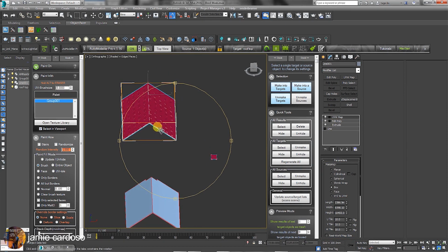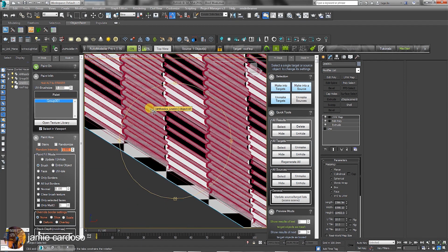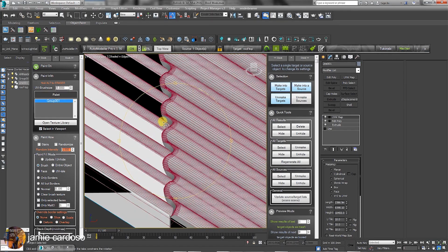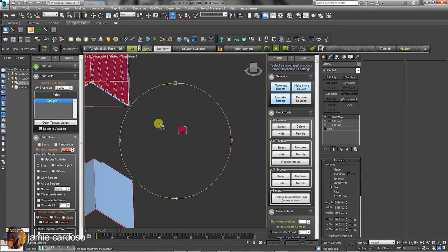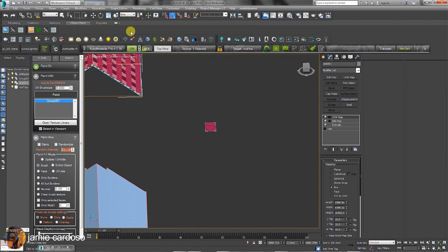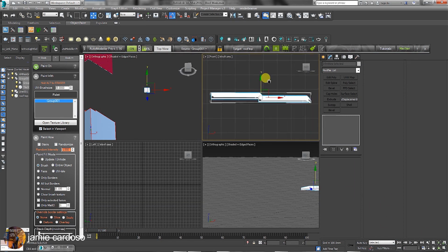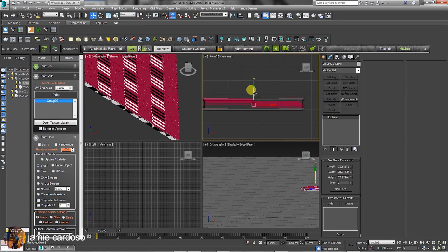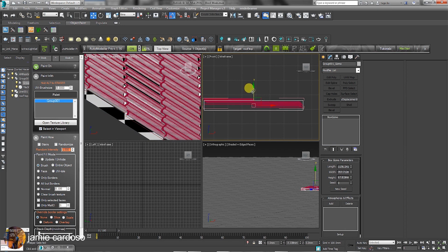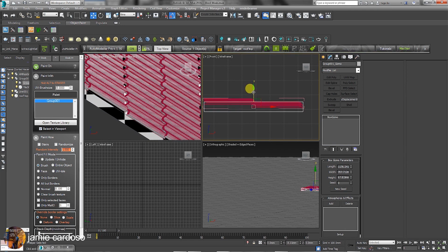If you zoom in closely, we'll notice that parts of the roof tiles are sunk into the main roof surface directly below. To correct this, let's first select the roof tile mesh gizmo previously created by the Automodeller plugin when it was first set as a mesh source. Next, in the front viewport, begin moving it down. As you can see, the tiles are beginning to sit on top of the roof nicely.